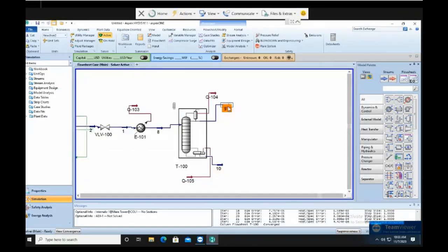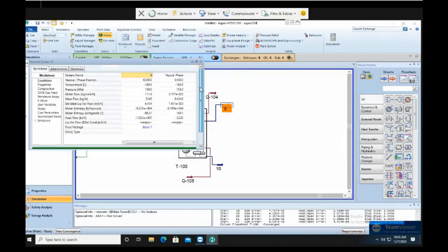So let's look at your number 9. The temperature, it has a bit of vapor phase, so later there will be a problem going into the compressor. The thing is that because your pressure is 1.5, unless you want to operate your second DC under vacuum, you can do that.